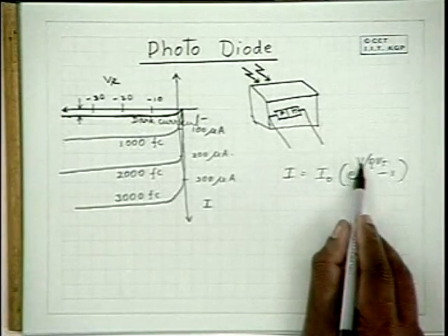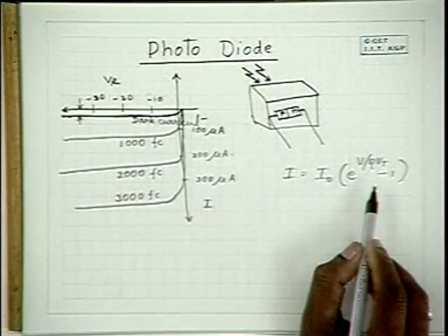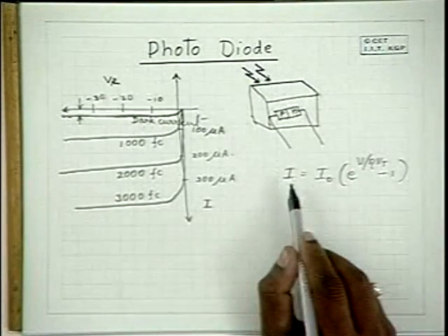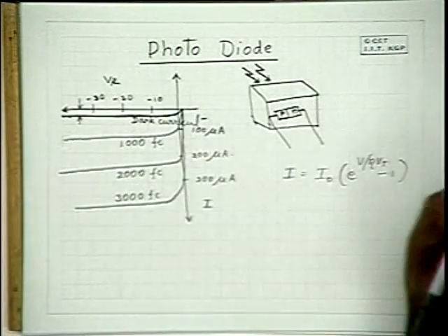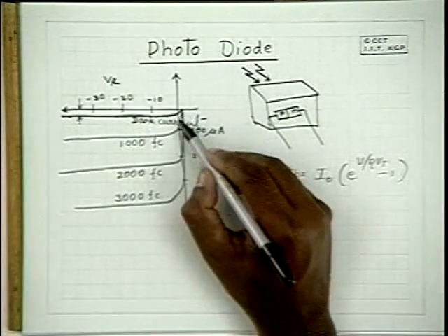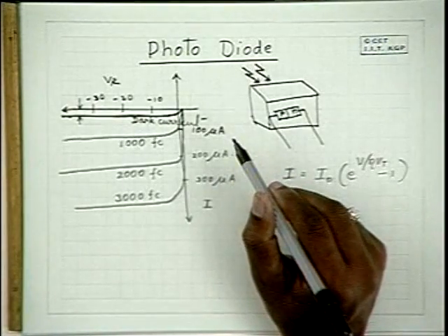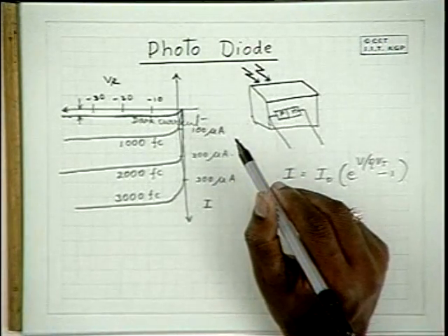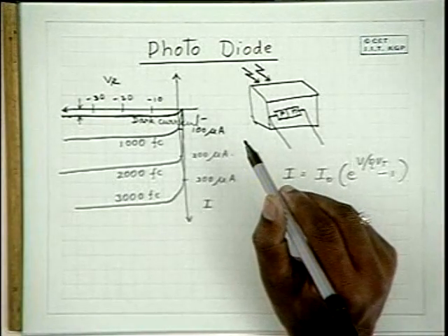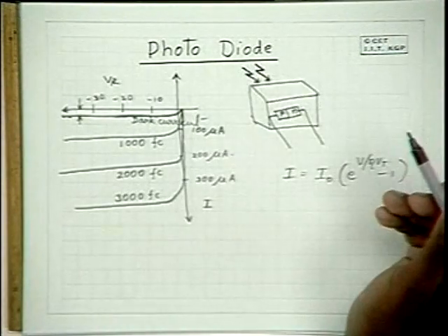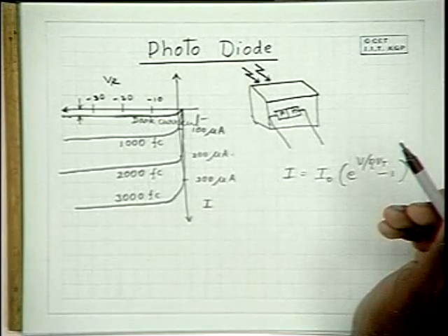Even for a slight amount of positive potential, you will find some amount of reverse current passing through because of the diffusion of the minority carriers. When the population increases, diffusion takes place apart from drift. For the charge carriers to drift, you need a potential difference.